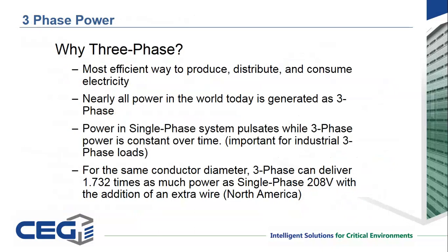A little bit more on that, right? It's the most efficient way to produce and distribute power and electricity, whether it's on the wires, whether it's coming into the building, whether it's coming out of a UPS. Inside a data center, you would have transformers in your power stream that can break down the voltages and lower them, as well as split up the phases and create different voltages for different applications and allow people to have power panels, the little breaker boxes that can distribute voltages that the transformers have stepped down.